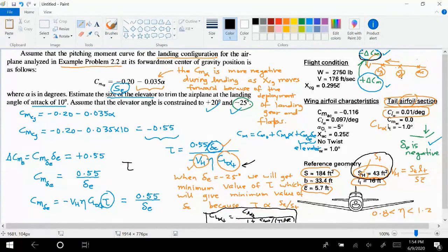In the project, you are trying to balance the extra moment which is created because of the single engine operation, because there one of the engines shuts down, so there is only one engine working. Some moment will be generated, so you have to overcome that extra moment using the rudder. Here you are overcoming this extra moment because of the landing gear deployment by using the elevator.